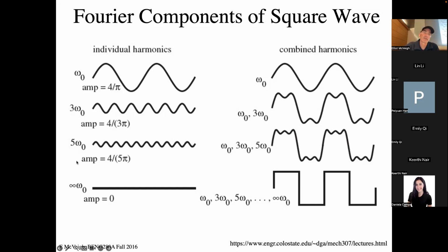In this case, we've substituted with omega. The kx is equal to omega. And say, well, what's the amplitude when we do the integral on this square wave with a sine wave at this frequency? And so here's our sine wave. We multiply it by this, do that integral, and we end up with some value. In this case, it's 4 over pi, right?